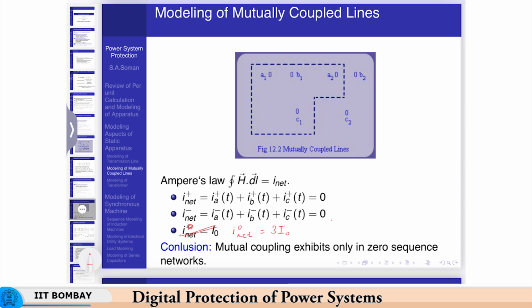This is very common, you have double circuit transmission lines, very commonly you can observe them whenever you see transmission lines. Here, for the sake of convenience, we are taking that the circuit 2 is not energized, that is the currents flowing in that circuit are 0. Now, due to the currents flowing in circuit 1, what is the flux linking the conductor in circuit 2?